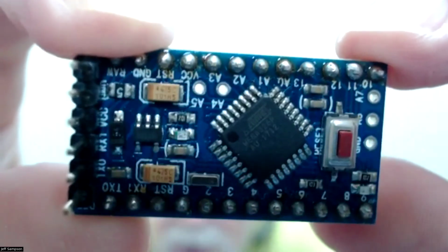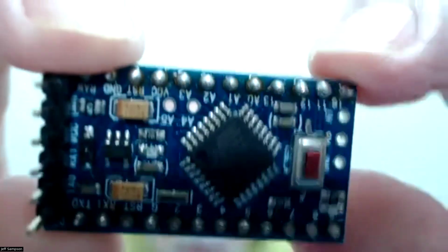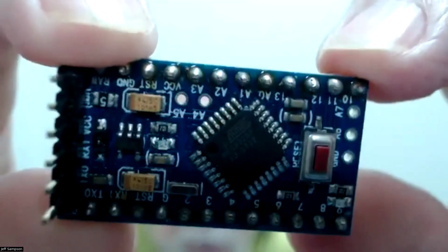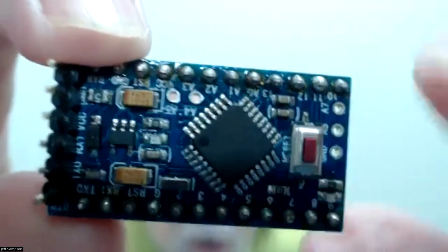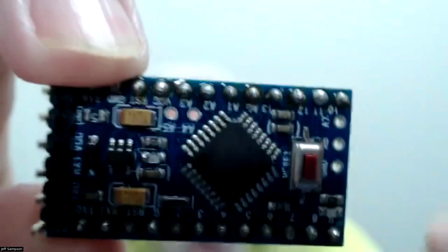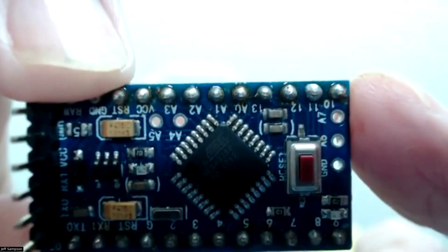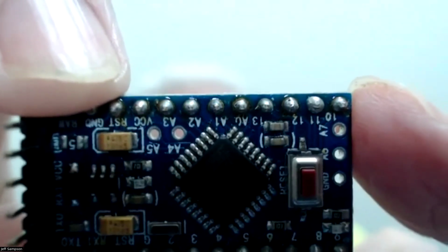And then there's 2 LEDs on the board. You've got your original pin 13 LED. Probably if you leave that on there and you don't program that as an output, it's not going to be a problem. But the power one's right across the power, so they're saying rip that off. Right next to that regulator, there's an LED and a resistor, I think a 1K resistor, in series with it. So that's something you can do on that.